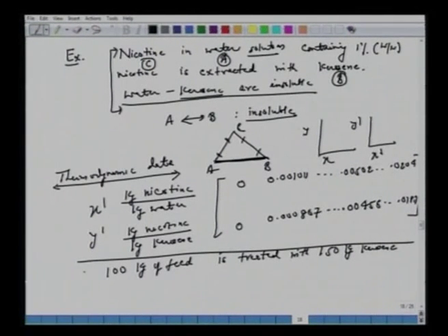All right. So this is step 1. Step B says the same 100 kg of feed is treated 3 times with 50 kg of kerosene. So the total amount of the solvent is the same, 150 kg. So one time you do it 1 time, and second time you do it 3 times. Take the raffinate, again treat with 50 kg, take the second raffinate, treat with 50 kg.